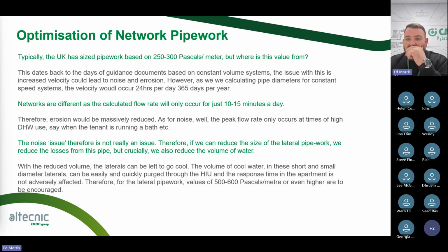Right. So, what diversity factors would you consider for domestic hot water sizing, and would you consider this a good idea instead of an HVAC standard? Also, would you consider diversified heating load when sizing the network? Okay. So when it comes to this, we always look at DS 439 because it's such a more stringent standard than what we have in the UK.